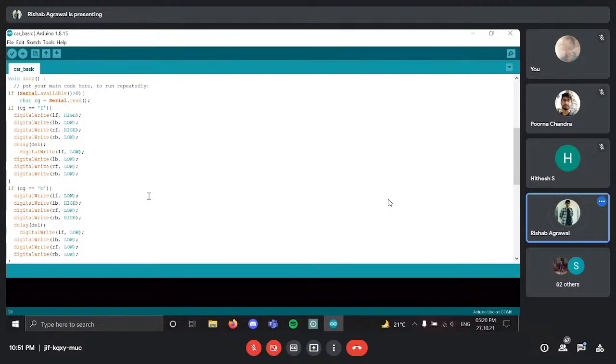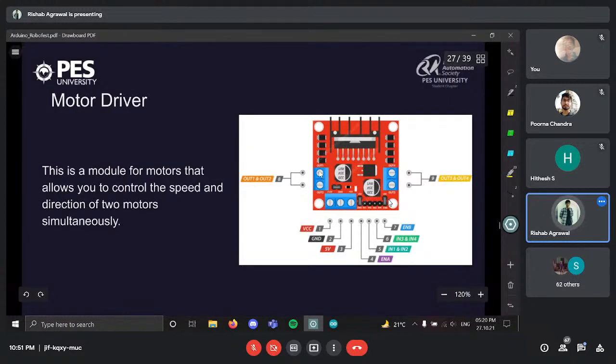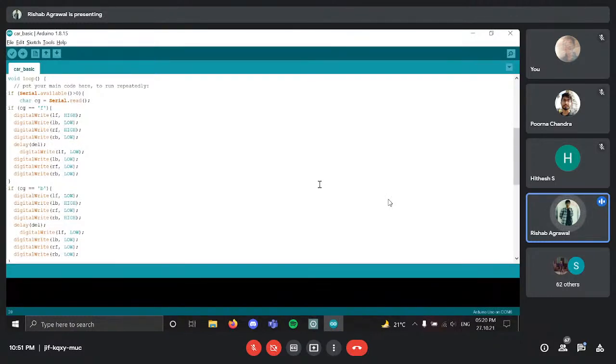But if you have switched the wires of the motors you have connected to output 1 and output 2, then it would run the opposite way to what you want. So rather than keeping all of that into account and getting it perfect at the first shot, which would be more energy consuming, you can just use trial and error and see what allows the car to actually move forward, given the directions in which the motors are rotating.